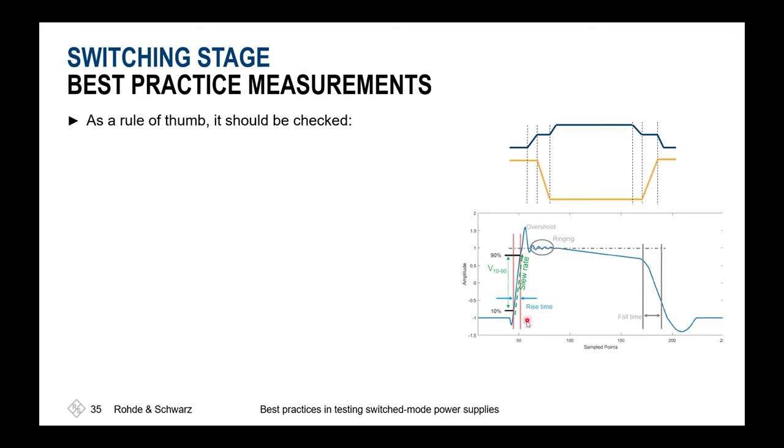This always means that you'll have to translate these other boundary conditions to your oscilloscope, which will give you a 10-90 value. So you could assume that your linear range of the oscilloscope is then faster, because this 10-90 value you could decrease to a 25-75 or something like that. So that's just a linear scale, and then you'll get the values for 25-75.